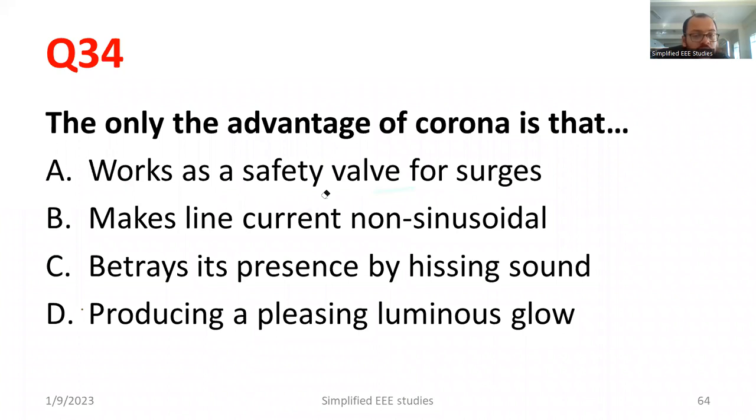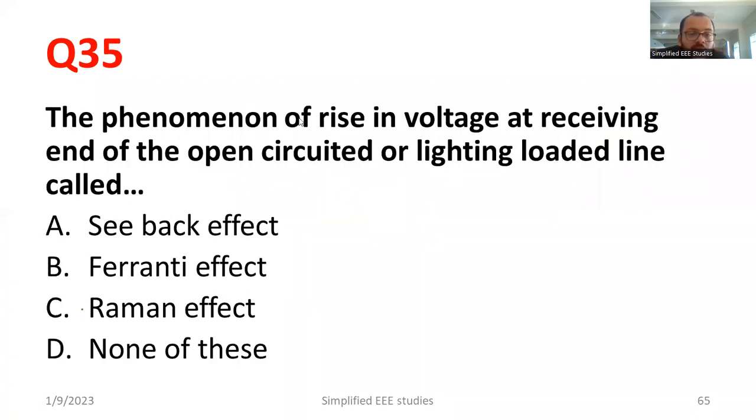So this is very important. Another question: the phenomenon of rise in voltage at the receiving end of an open-circuited or lightly loaded line is called the Ferranti effect. Due to the Ferranti effect, because there is a certain amount of capacitance present inside the transmission line, the receiving end voltage exceeds the sending end voltage. This effect is known as the Ferranti effect.